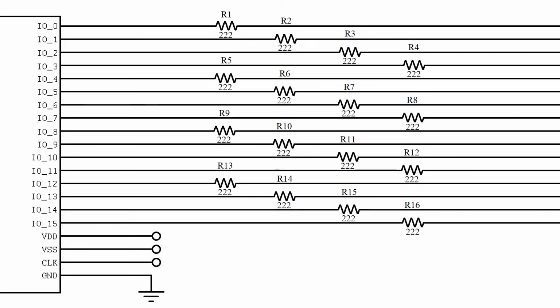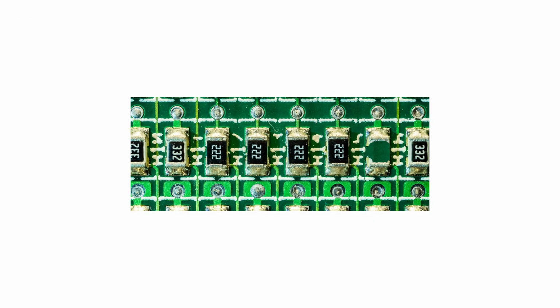Looking at the schematic, this is IO1 data line. Following this data line, we're going to come to a resistor. Now let's look at our board. So we notice that this is a surface mount resistor, and it looks broken. So this must be the source of the problem.